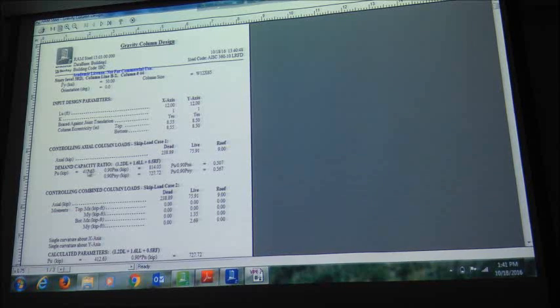Right? With 1.2, 1.6 and 1.5, that's the load combination. And my phi PNX is 814 kip and phi PNY is 727 kip. Obviously it's larger than 412. So remember, in our class I said maybe 50-20% more, doesn't matter. Okay? It's actually almost 200% more.